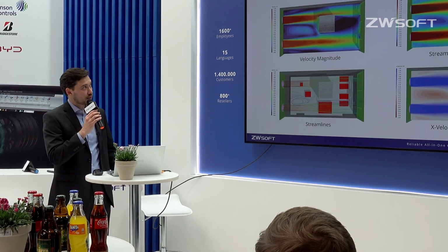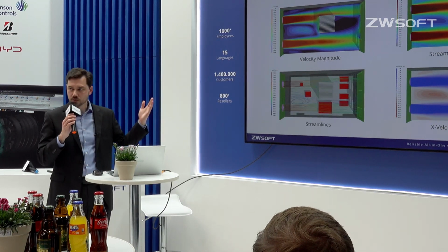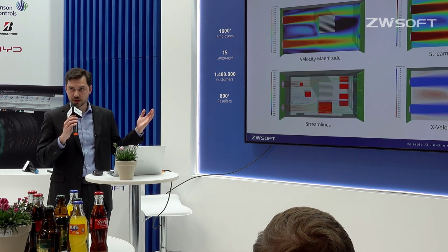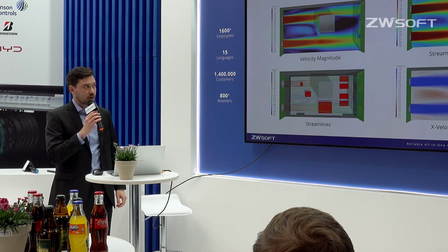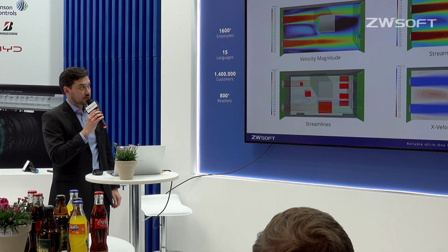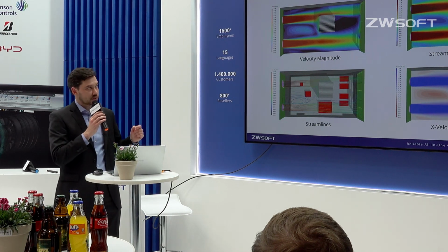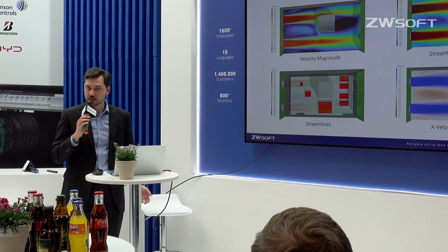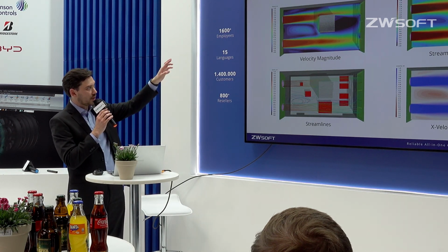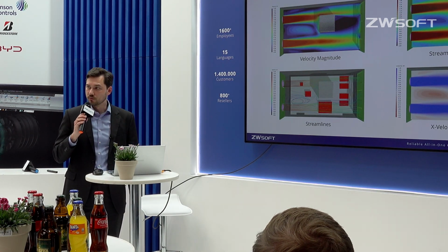We then also see that the top jet doesn't really interact particularly much with the heatsink. It only really touches maybe the top third. So the next feature that I'll dive into in a sec is that we also have a very big dark blue region behind the heatsink. This signifies, with this legend that we have here, a close to zero velocity region.